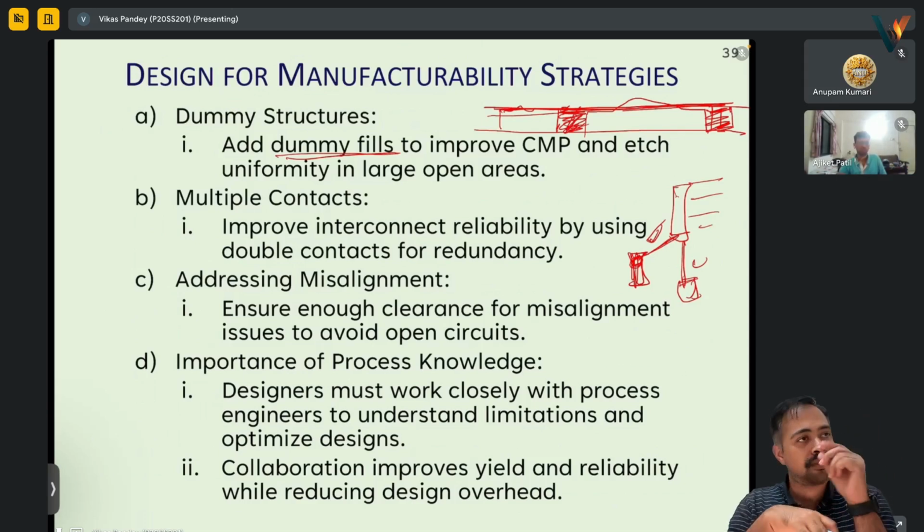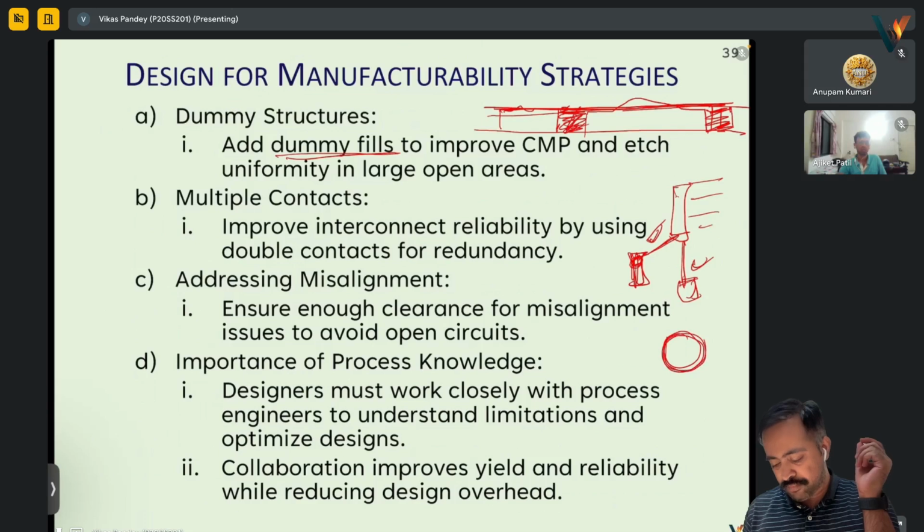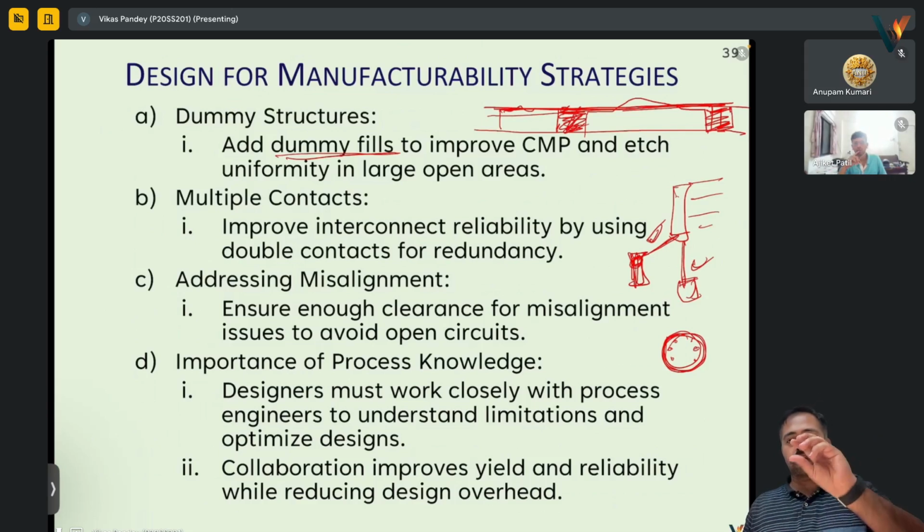That's why sometimes you might see, in case of transistor packaging, a header is used which will have six legs coming out. Ideally, we have three terminals only: source, drain, and gate. But all of these terminals are connected to two pins, so at least one of them will work. Such things are used to ensure reliability. That saves cost because the rejection ratio and the breakage will reduce.